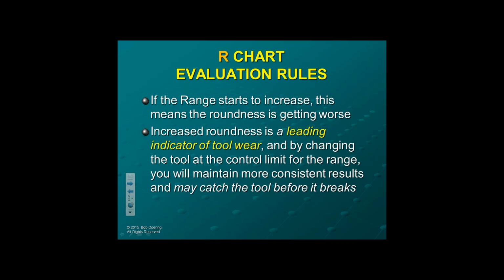Also, the more it rubs, the more it starts to generate heat, and it's going to create heat to either harden and crack or just simply essentially explode the cutting edge of that part. So when you see this happening, you can actually tell by experience when there's enough roundness occurring to pull that tool out before it breaks.